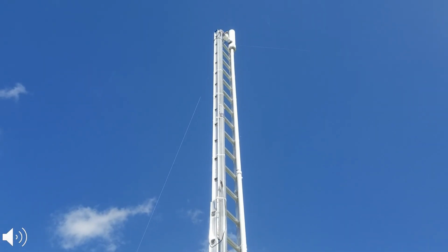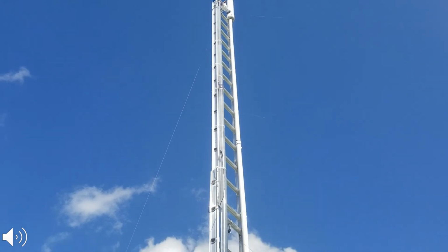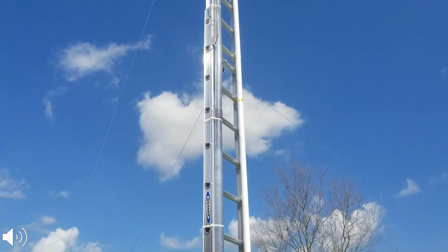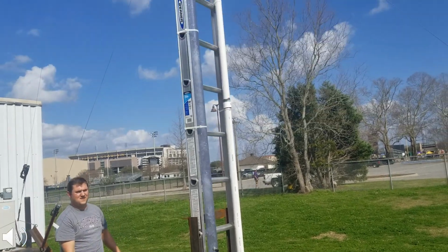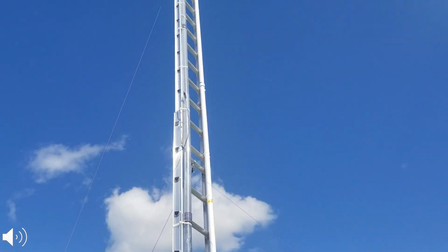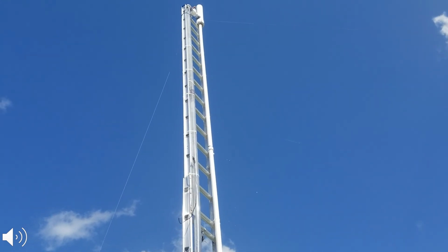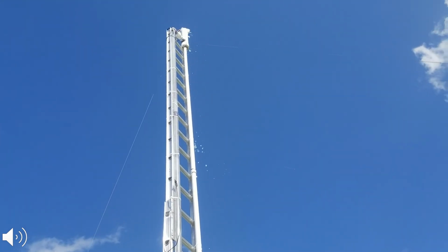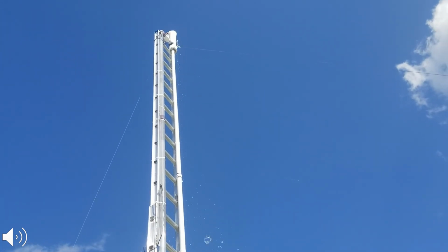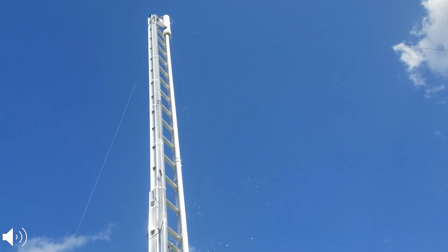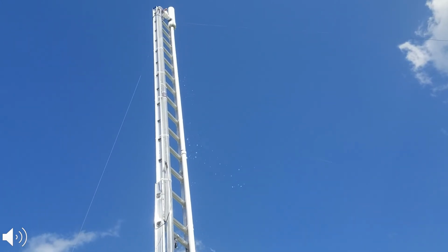The riser portion is constructed of 2-inch Schedule 80 PVC pipe with 1.5-inch Schedule 40 PVC pipe as a return line. The water is pumped with a 15-gallon per minute centrifugal pump. The air is injected through a 40 to 400 SCFH flow meter. There are three 0 to 200 PSIG pressure transducers that are mounted along the side of the riser to allow for pressure readings at different points in the riser.